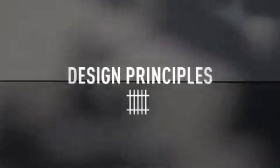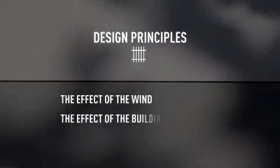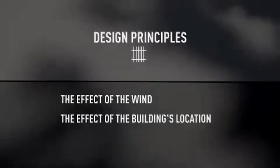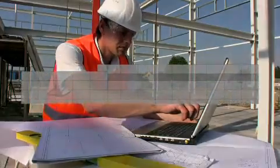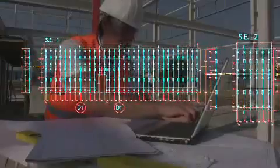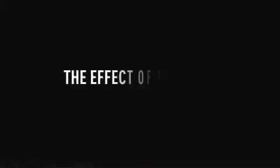Design principles. The designer or engineer needs to consider a number of factors, such as the effect of the wind and the building's location. Referring to the architect's drawings, the engineer will calculate and design the framing based on the panel layout. This design will show the position of the profiles, brackets, fixings, and any special details. The effect of the wind.